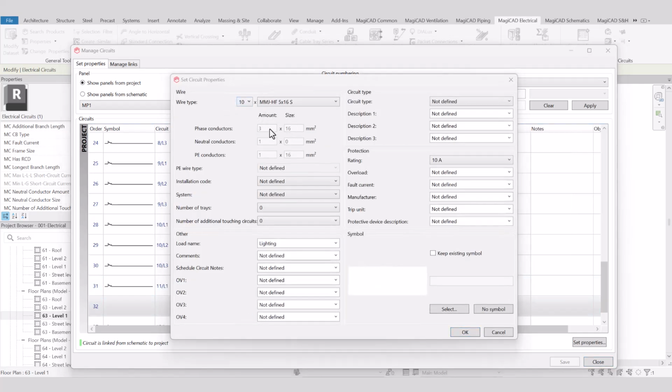And the weight per meter property is used to determine if a wire type should be considered a cable product, and the conductor arrangement dictates if the cable is considered a multi-core cable or a single-core cable. All the settings for single-core cables are taken into account in the bill of materials and cable out functions and when transferring electrical data to external calculation software.